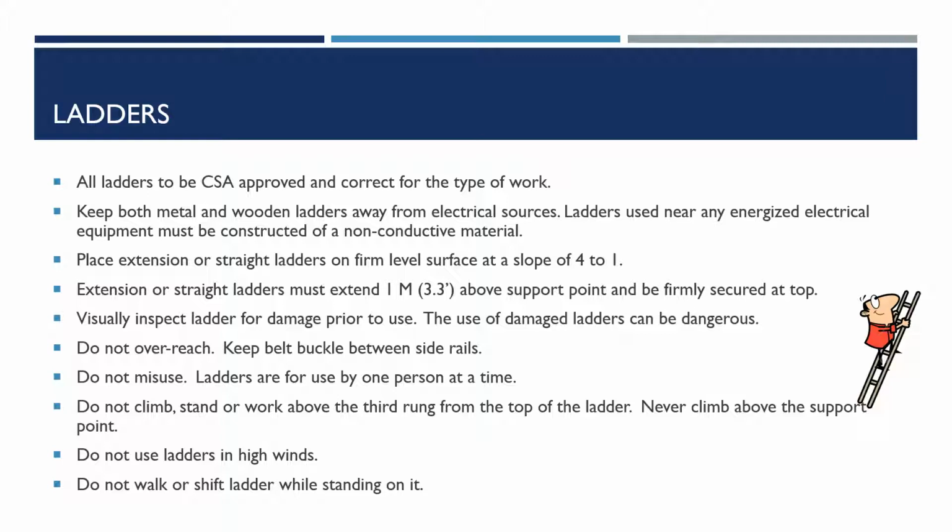The use of damaged ladders can be dangerous. Do not overreach. Keep your belt buckle between the side rails. Do not misuse. Ladders are for use by one person at a time. Do not climb, stand, or work above the third rung from the top of the ladder. Never climb above the support point. Do not use ladders in high winds, and do not walk or shift the ladder while standing on it.